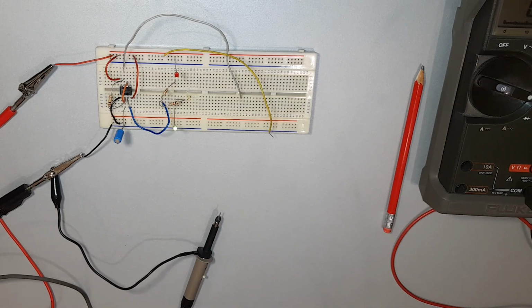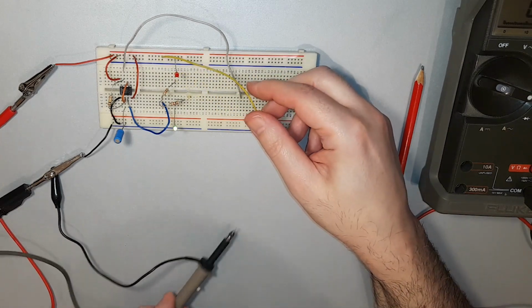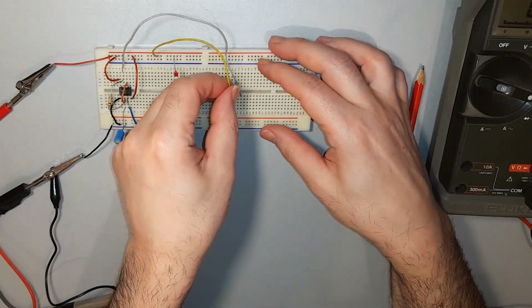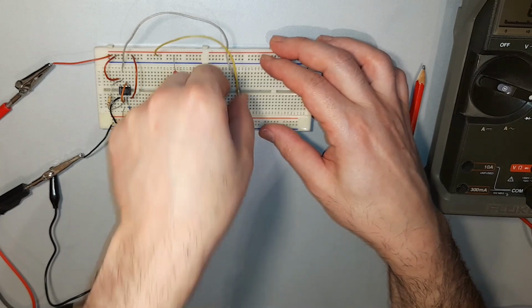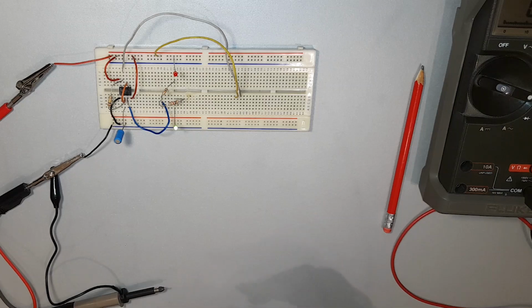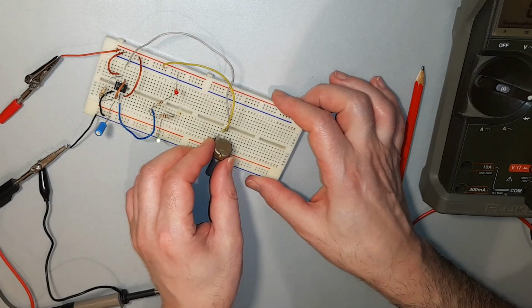Right. Oh, that's good. So it was the chip that is shorted. It doesn't like being shorted like that on pin 7. So pin 7 has to have a resistor of more than a few ohms in place.